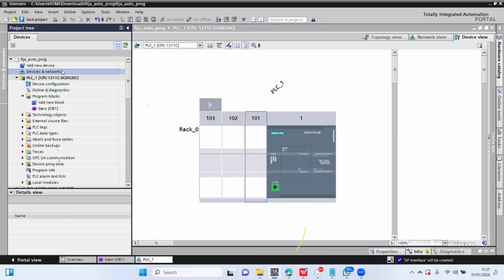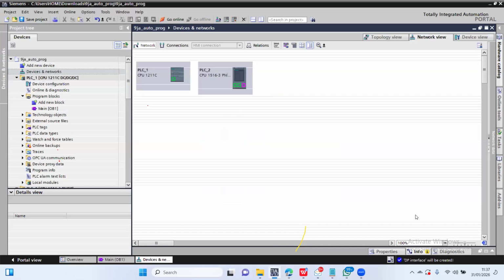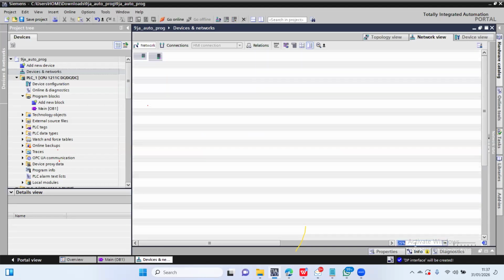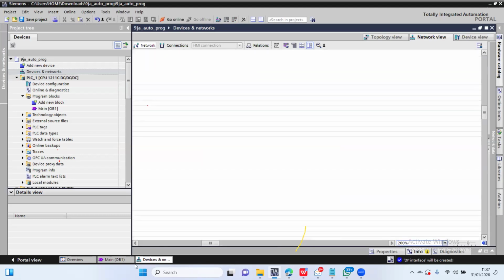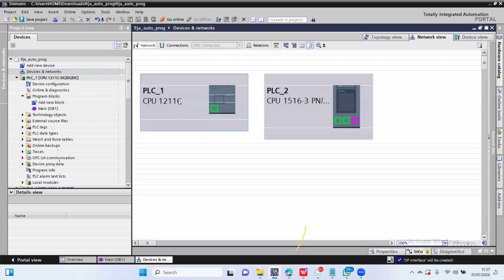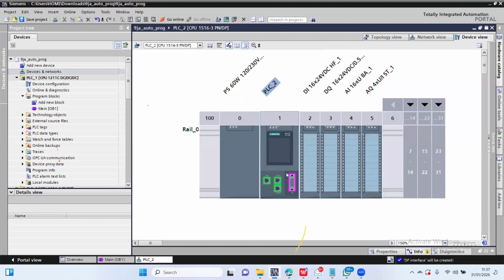But just so that you see, this is the TIA Portal software. I don't know if you can see very clearly. So here, this is just a small one, you can see we have the CPU, the S7-1200. Then here we have our S7-1500, which is a modular PLC, like I explained, right? And here you can see that apart from the ones I showed in that image, you can also see an extra serial port. If I want to extend, I can just simply add an IO here.